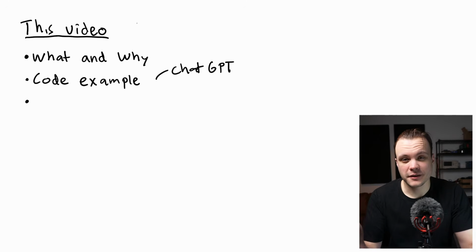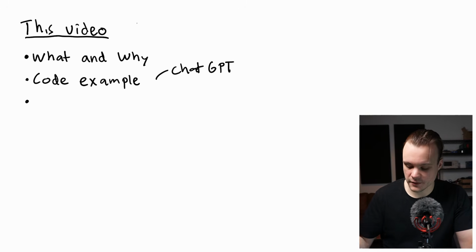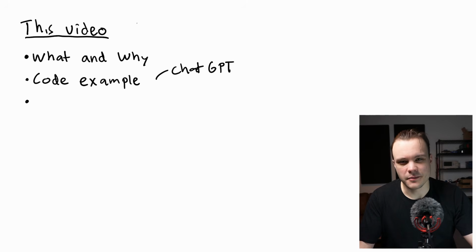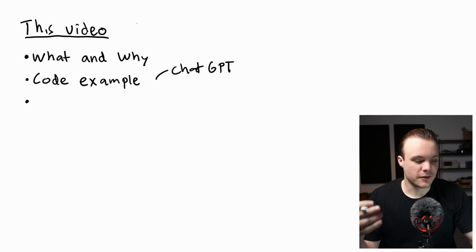In my project code, I'm going to add a couple of functions to make it easier to register new interrupts to my GPIO pins. Normally when you add an interrupt, you have to write to the registers of the microcontroller directly, which is a bit cumbersome. As I did in the video where I show how I program GPIO pins, if you haven't watched that, go check it out, I like to write some C code or an abstraction layer that makes it more pleasant for me as a programmer to work with the IO pins. So I'm going to do something similar for registering interrupts.